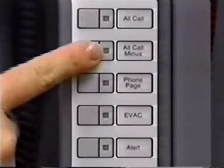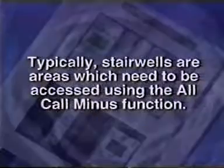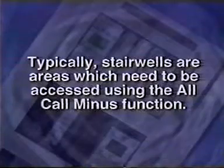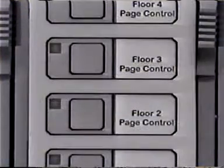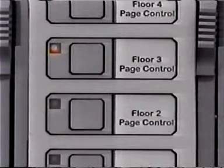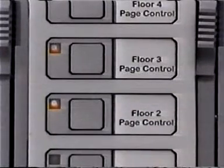Finally, use the all-call minus function to make announcements to areas of the facility not receiving the evac or alert signals as required. Typically, stairwells are areas which need to be accessed using the all-call minus function. If your system is equipped with zone page controls, which may be configured as control LED displays, they may also be used to manually select paging areas.